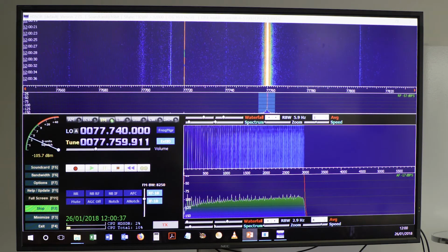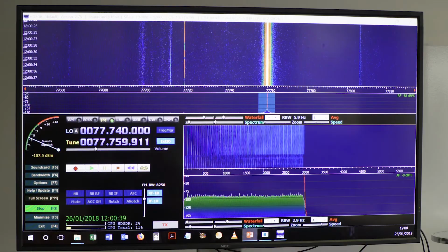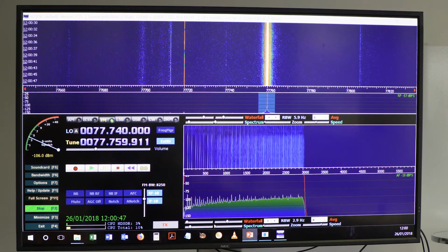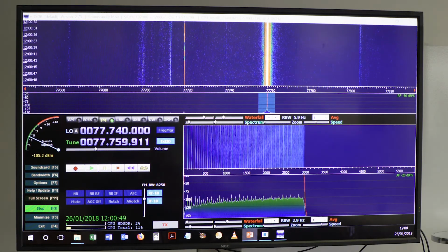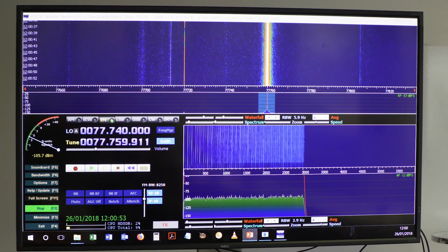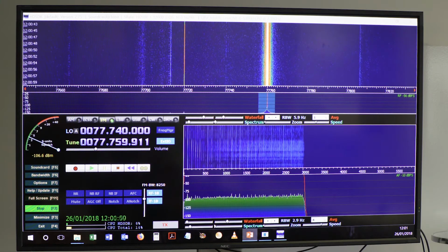Because I am masking the two antennas by putting my piece of metal there. You might think that I'm improving the antenna because I'm putting a reflector behind the antenna. So you might say it's going to be better. But in fact, as you can see, it's reducing the power. Not so much, but it's slightly reducing the power. Okay?